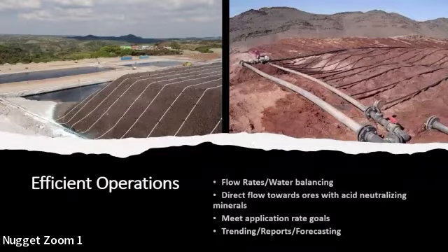With this particular sample here, it did remain above the 100x safety factor until about 60 feet below the heap surface, whereas the others drop below that. So just to summarize what I just showed you in a table, this shows the sample, the 100x forecasting irrigation rate, and then the forecasting irrigation rate. Where it's green highlighted, that's positive, that's great. Yellow is marginal performance in terms of permeability, and red is it really fails at what we'd like to see. So again, the SP ores look good, so should not have percolation issues.